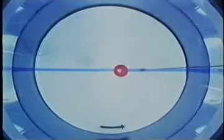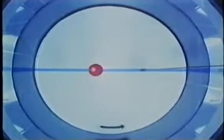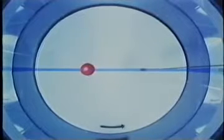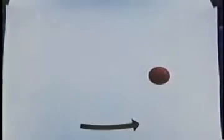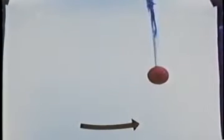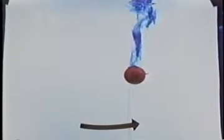At low Rossby number, pressure reactions build up a horizontal pressure gradient, which exactly compensates the Coriolis force on the sphere, so that it moves straight across. The reasons are associated with the flow pattern around the sphere. Here we are looking from the side. Dye crystals leave traces which mark the fluid over the ball. When the ball is towed away, it does not leave all the dye behind as we might expect, but instead carries a column of fluid with it.